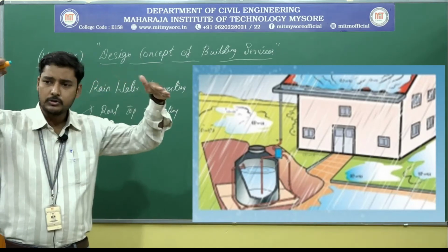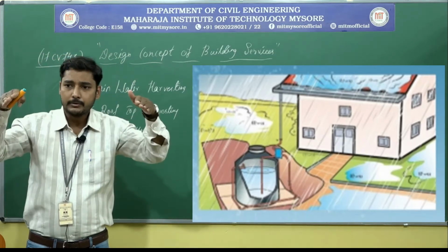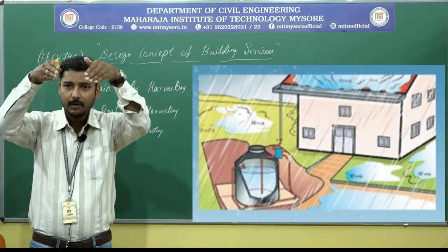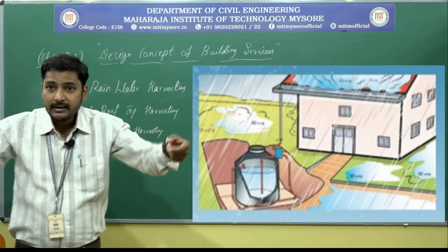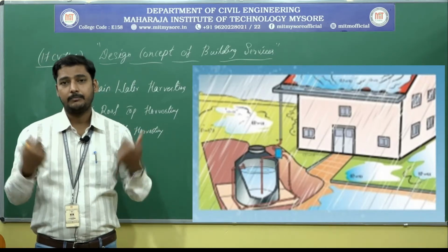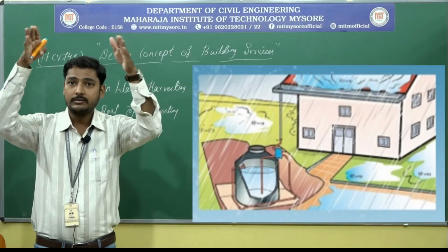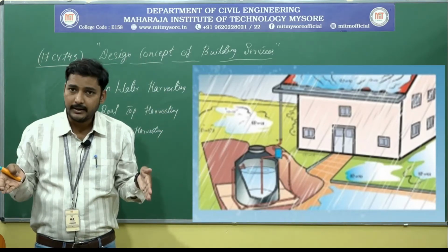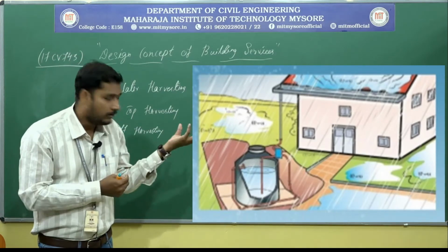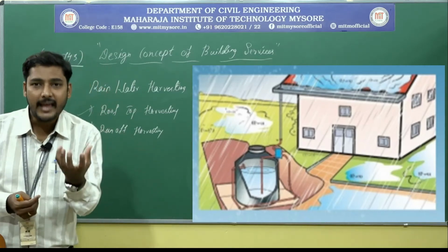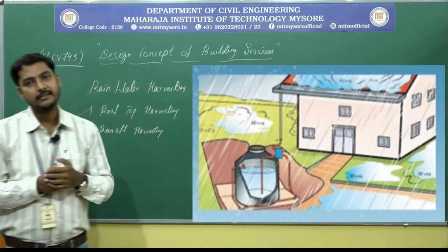Of course, the topmost part in turn experiences that rainfall. By providing proper slopes on either side, the water, once it drops on that surface, will in turn go to the end, no doubt. Then at the end we need to give collecting pipes, or provide gutters or pipelines, so that the entire water gets collected through that pipeline and comes to one particular corner. Yes, we can observe in this figure at one particular point we can have that collecting tank.